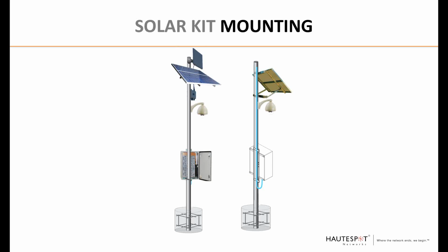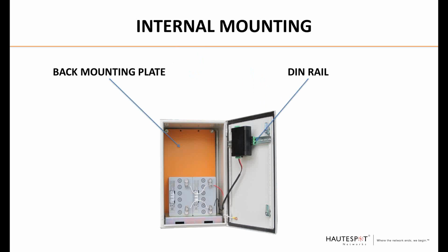So here's what the overall system looks like when mounted. More than likely, you will have a hotspot wireless gear installed on this solar job. Generally, you want the wireless panel antenna to be installed highest on the pole. If this will cause significant shading in that 9 a.m. to 3 p.m. time slot, consider installing the wireless panel below the solar panel, making sure that the wireless antenna is not being blocked by the solar panel.